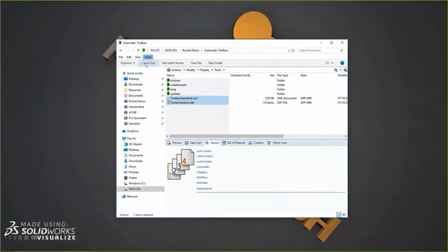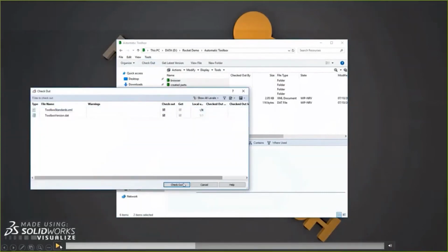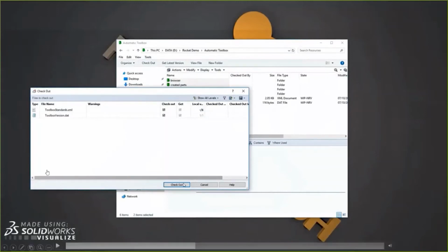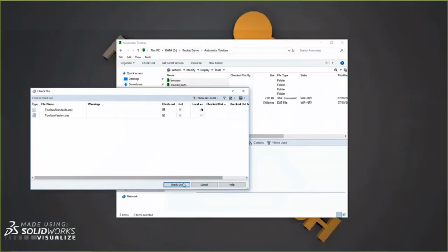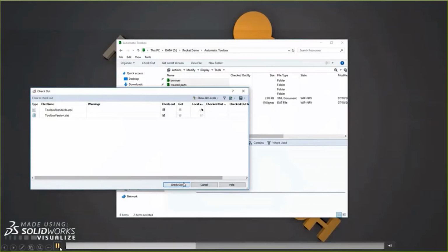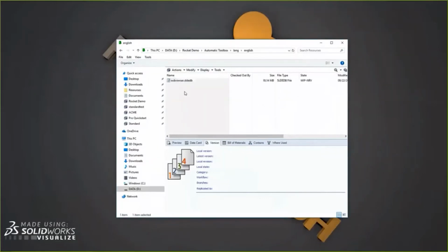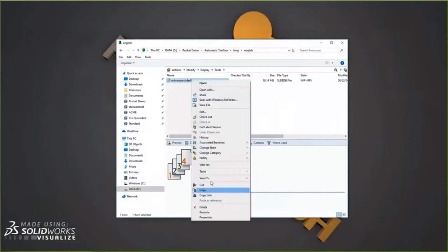So I'm going to check out a few files. If you guys have tried to do this following the admin guide, I know it just tells you to check out one file. There are a few other files that you want to check out. Some of these are just logs, so it's not going to error out if you don't check them out. I like to check out all of the files because, A, then my logs are properly updated. So I actually get in that toolbox version, I get that log updated and it's not just putting in a new file. And I've seen fewer errors when doing it this way than when just checking out the single file. And that single file that they want you to always check out no matter what you're doing, you have to check out this SW browser file.